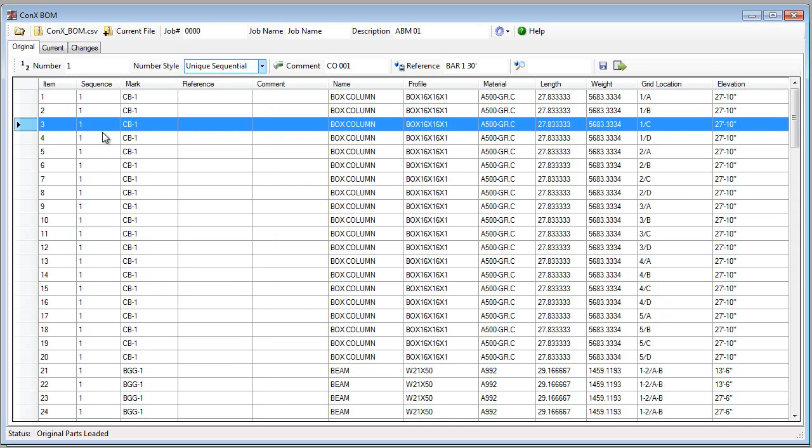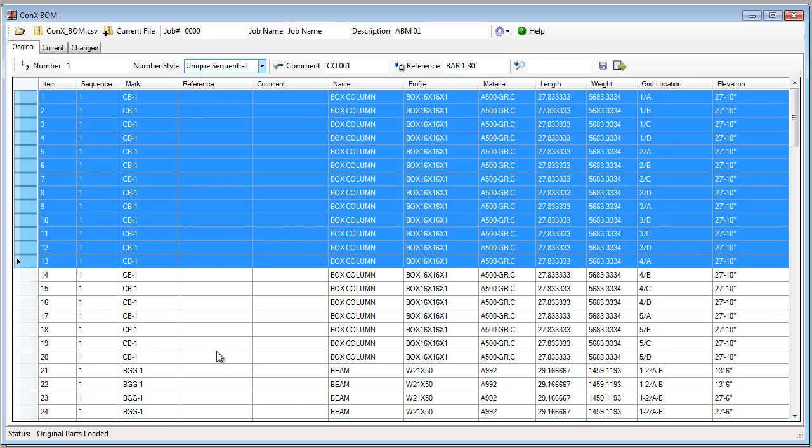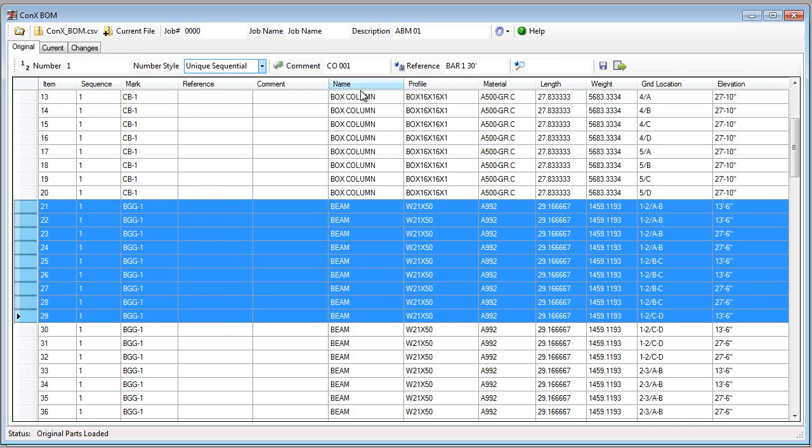Okay, one other neat thing that you can do here is, once you set the requisition form or the summary report to the service center you're working with or the mill, they can give you a cut list or show you a nest report that basically says each of your pieces with their item numbers or the lengths of pieces in the profile, what they fit that to as far as a cut list, or what bar they are associating that to. So on your reference you can say bar number and then the length as a reference, and then you can select all those pieces here in the model. So let's say that I have some beams down here. I can just come in here and say that these are all cut from the same bar.